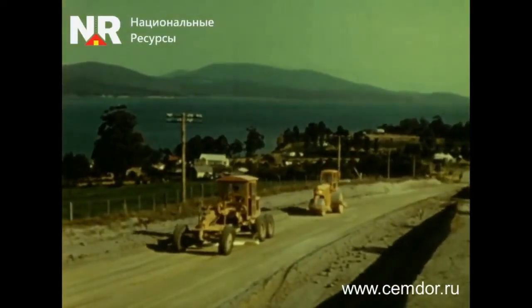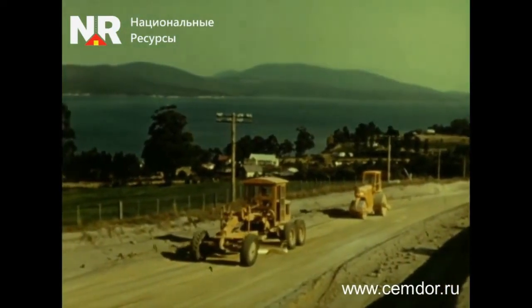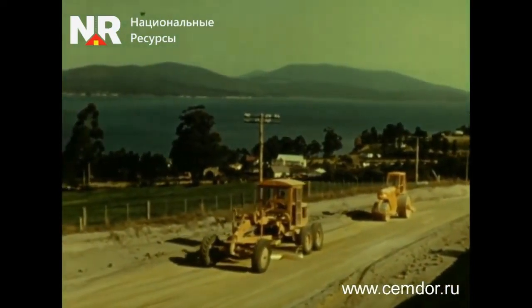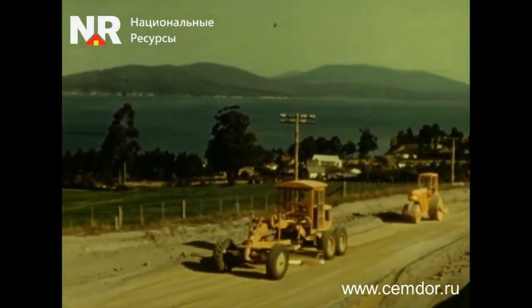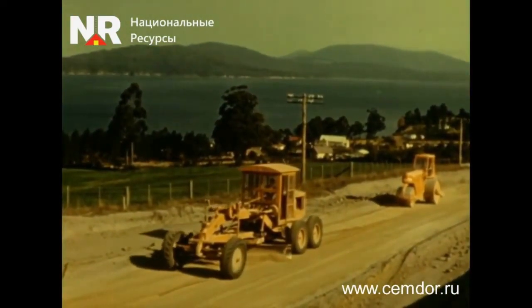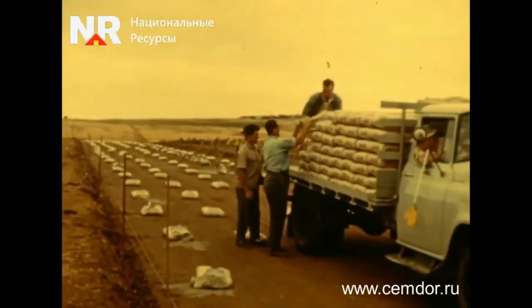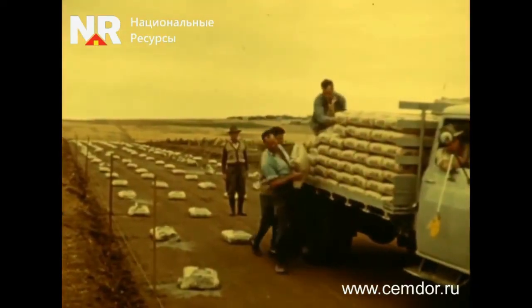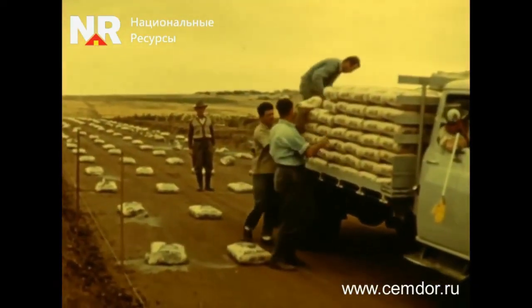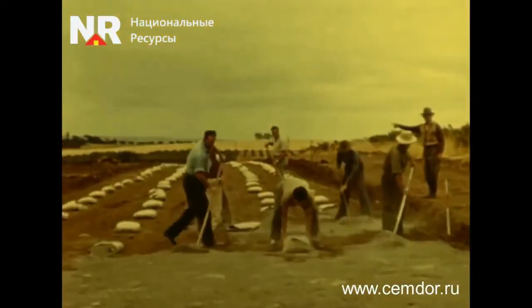Construction of a soil cement road begins with preparing a base of the required thickness and cross slope using either local or imported soil. Proper compaction of the base is an important technological step. The cement required for the road surface can be delivered by truck in bags. The bags are laid out along a specific path and then opened.